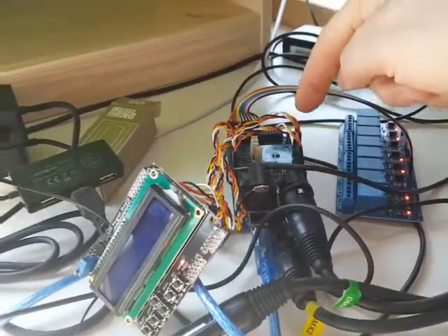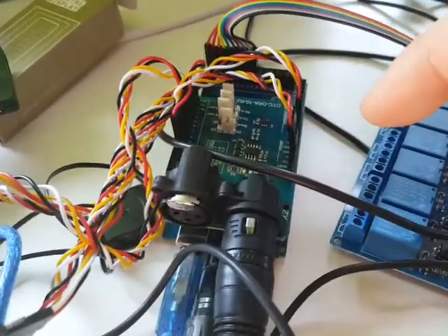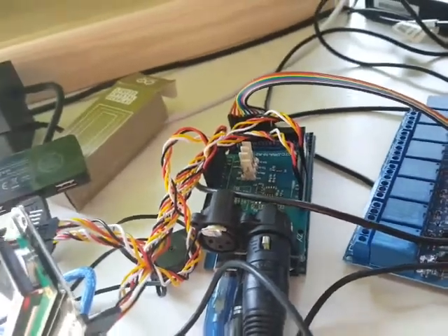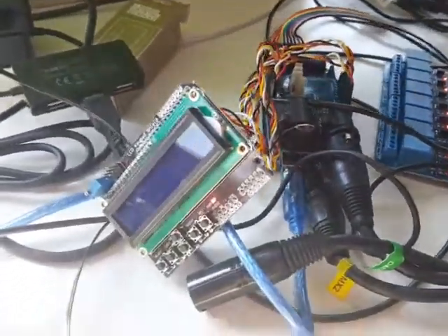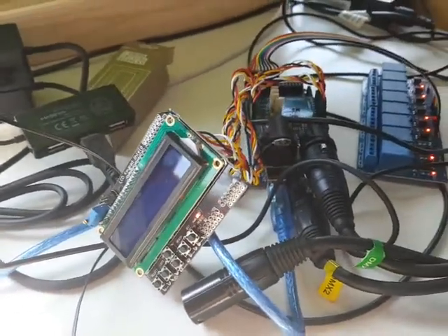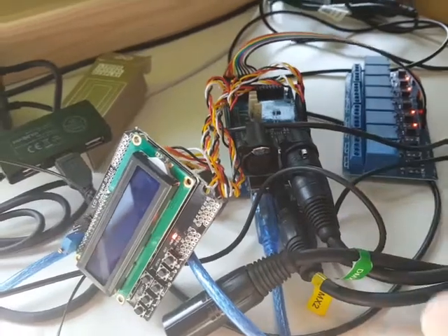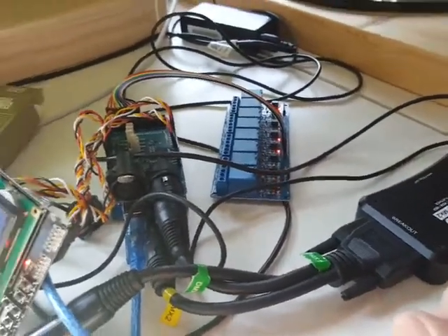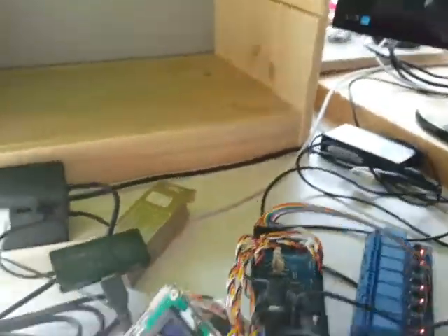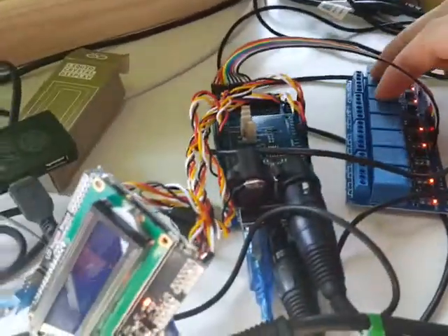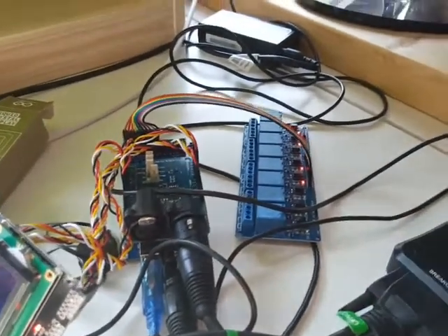I'm using an Arduino Mega, one DMX shield, a CTC DRA 10R2 from Concept Dynamics. And then I have an LCD keypad shield connected on the Arduino, and here DMX is coming in. This could be any DMX device, with software or without software, just a normal DMX table. I'm using 4 DMX channels.